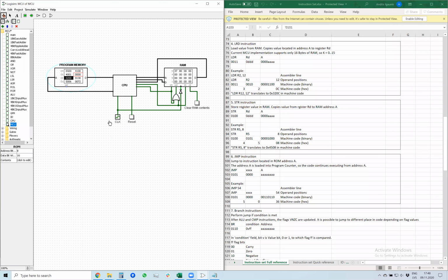So if I write it here, 5007, then let's reset our processor. Let's run the program again, and let's see what happens when we reach this location. So the first instruction was load number 37 in hex to register number 1. Next is load number 67 in hex to register number 0. The next instruction was something like copy the value, then add two registers together.